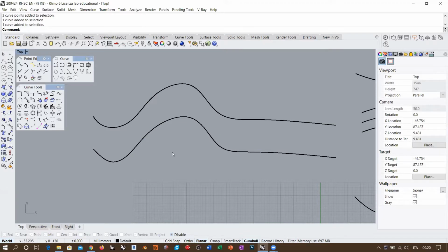And the message that I want to give you is that rebuilding the curve is not always the best option that you have. Of course, there are situations that we are going to study in which the rebuild curve is the only way you can simplify things or make things more suitable for a regular workflow. But in general, I do prefer to perform direct topological operation instead of rebuilding the curve. So this is the point where we are going to get in a while. And then eventually we will discuss other things, but I think they are less relevant.